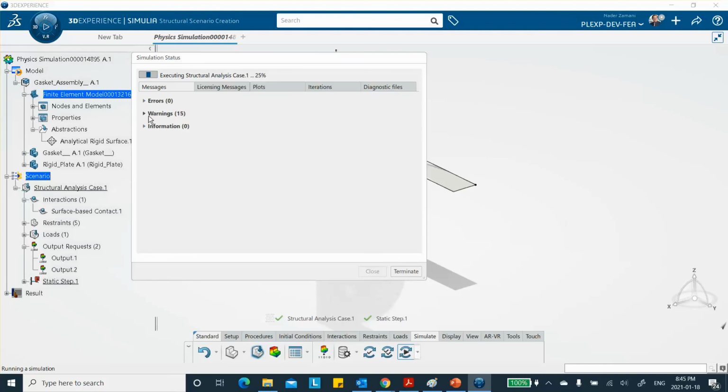Now notice that it's going further. That's because this is actually a nonlinear problem. It's going to do it in increments, and within each increment, it has to do iteration so that the results converge. So it's a fairly laborious process. It's not just like a linear analysis that it just does in one shot. Okay, we're going to be done. If your problem is big, too many elements, etc., this thing can take very long. We talk about sometimes maybe an hour. But these are simple problems. We're not going to be worried about it.